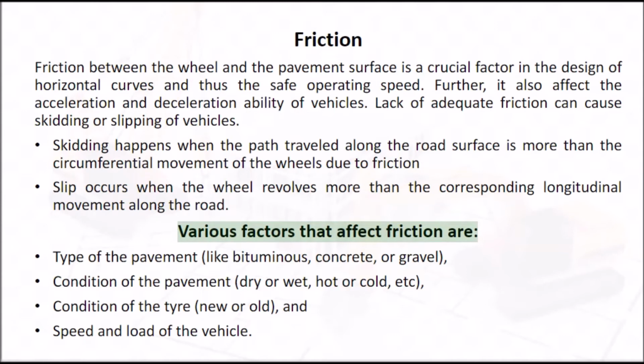Various factors that affect friction are: type of the pavement, like bituminous, concrete, or gravel; condition of the pavement, dry or wet, hot or cold, etc.; condition of the tire, new or old; and speed and load of the vehicle.